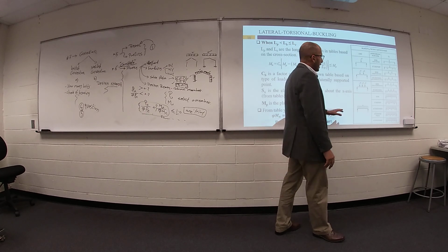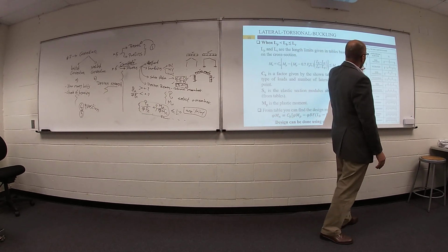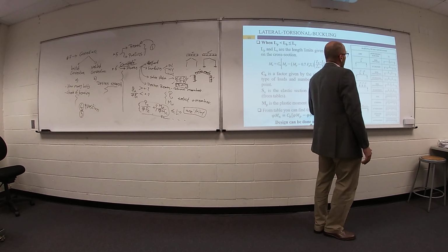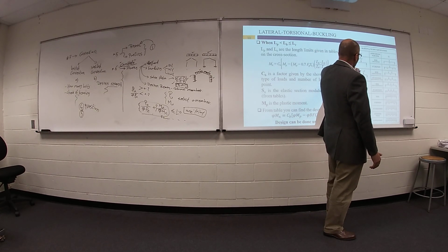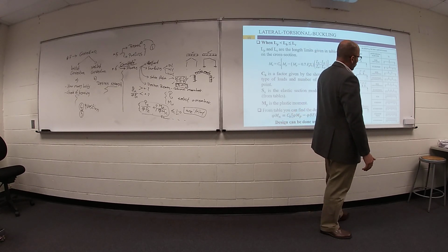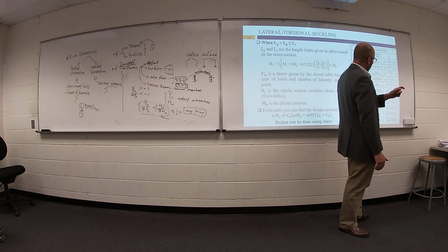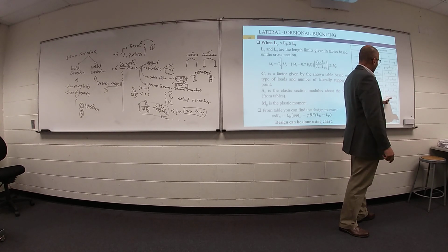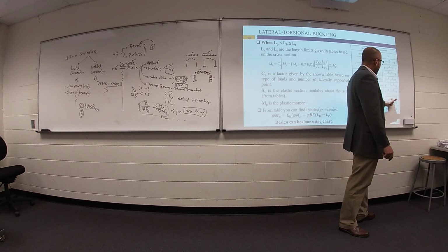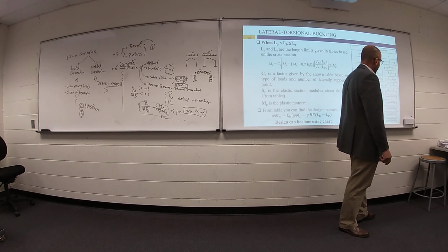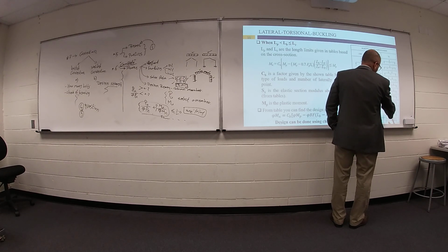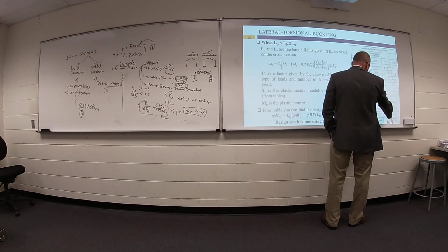If not, open this table from your notes and try to figure out the type of your load. Is it one concentrated load, two concentrated, three concentrated, or distributed? If it's a distributed load, with lateral support for your flange at the two ends only, your CB equals 1.14. If you have an intermediate support, 1.3. If you have many intermediate supports, we have a different value.